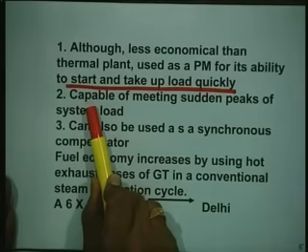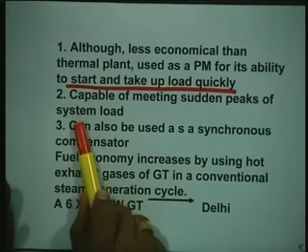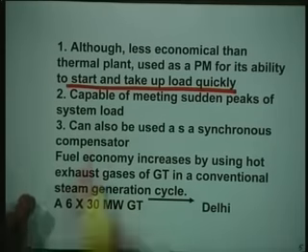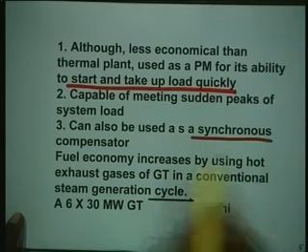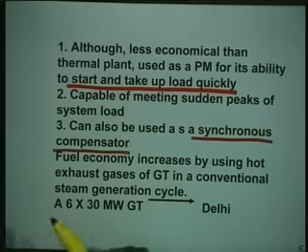It is very much capable of meeting sudden peaks of system load. It is very quick starting. It can also be used as a synchronous compensator. What is a synchronous compensator? Have you heard of synchronous compensator? You must have read it in your synchronous machine or in power system course in your 4th year. This is also called dynamic compensator. There are 2 types of compensation. Compensation of what? It is not power factor, it is 3 in 1. It is voltage, it is power factor, it improves efficiency also.